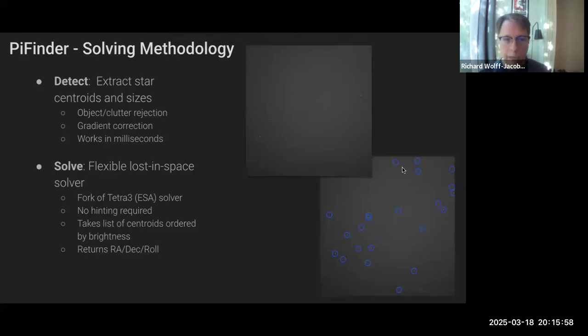So it's called centroiding. It figures out what looks like a star in that image based on a lot of factors. There's some really fun stuff about rejecting trees and airplanes and other stuff that is a deep area of its own. I'm going to gloss past that and just say that the centroiding produces an XY coordinate list of stars plus their perceived brightness by the sensor.